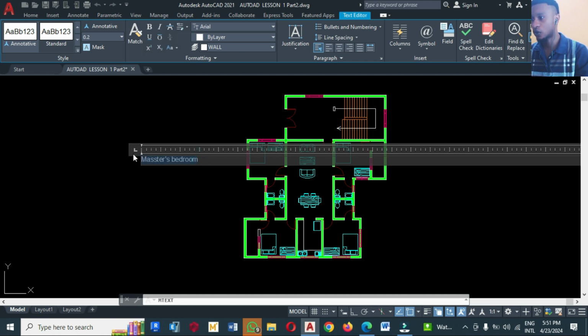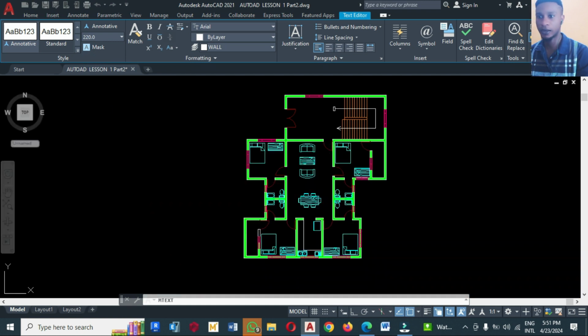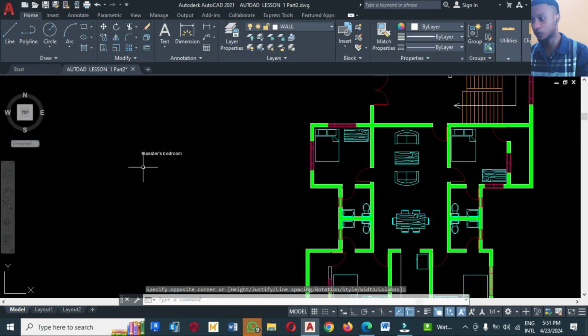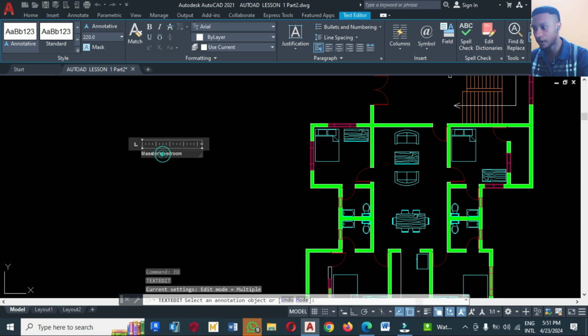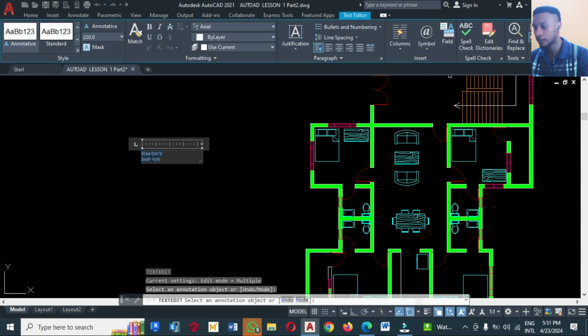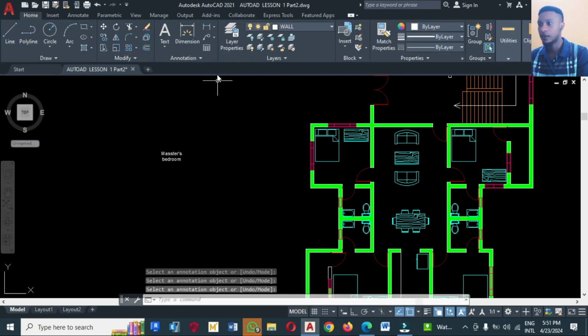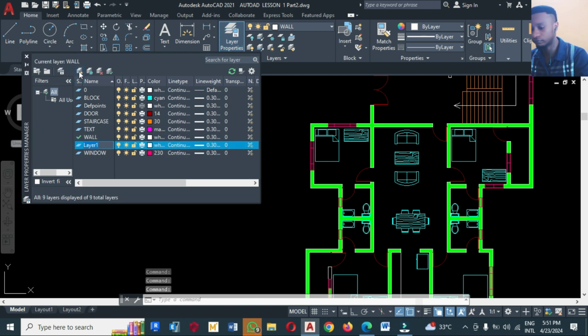Alright, so let's see how small and how big. Let's check dimension. Let's select this. If that is too big, we can reduce it. It's not too big, so okay, I'm going to now break it into two. Now I'm going to edit this. That is ED for edit, and enter like this. I can change it to center, so select all, centralize. Okay, and then I can give a different layer, like label. Let's call it label.